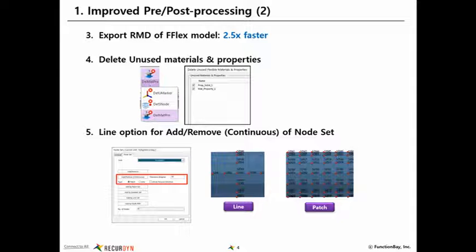And since it's an ASCII file, if you are wondering about differences between two different models, by exporting the RMD file from each of the models, then you can use whatever tools at your disposal to do a comparison of these two ASCII files. Or you could go to a certain section of the file and do some kind of comparison on that from one model to the next. But anyway, if you ever want to have access to an ASCII representation of the model, that's what the RMD file is available for.